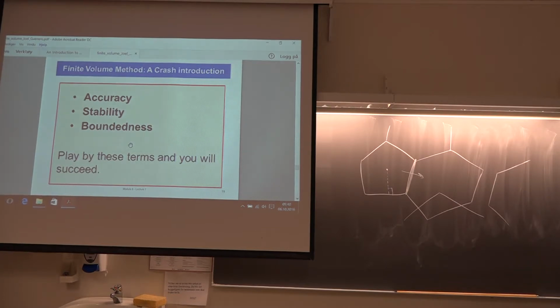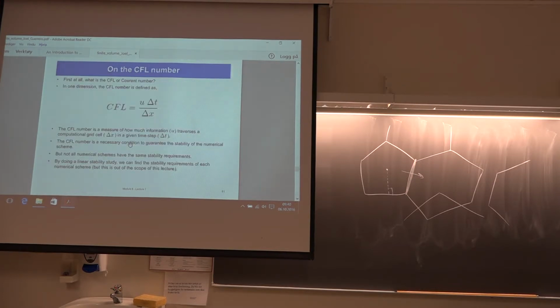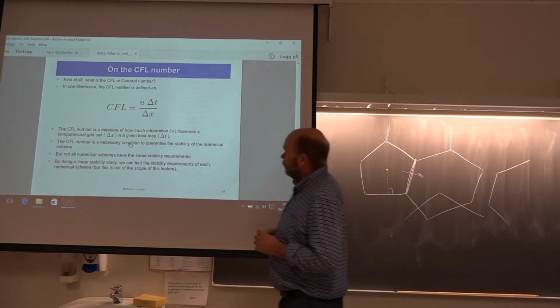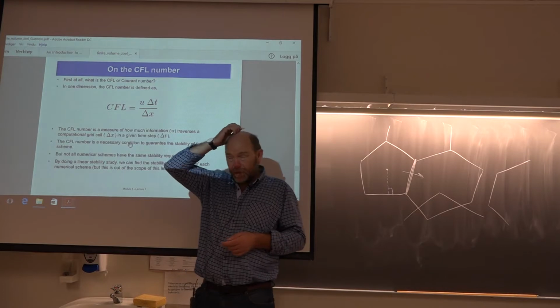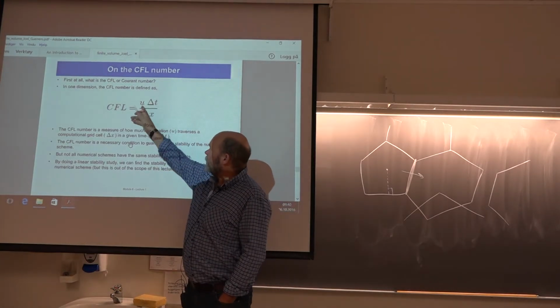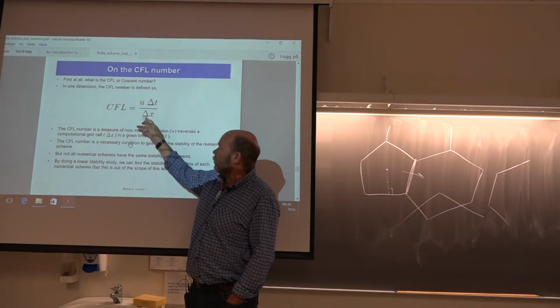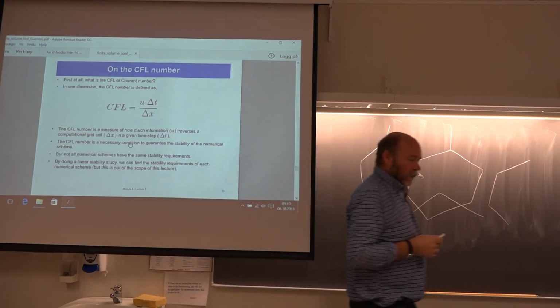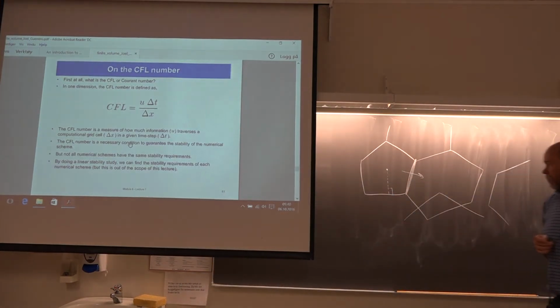So here, as he says, play with these and you will succeed. Yeah, the Courant number here, we can have a talk about it. The Courant number, yes, we have discussed this earlier. Physically, it means you should not travel longer than one single cell length throughout one single time step.